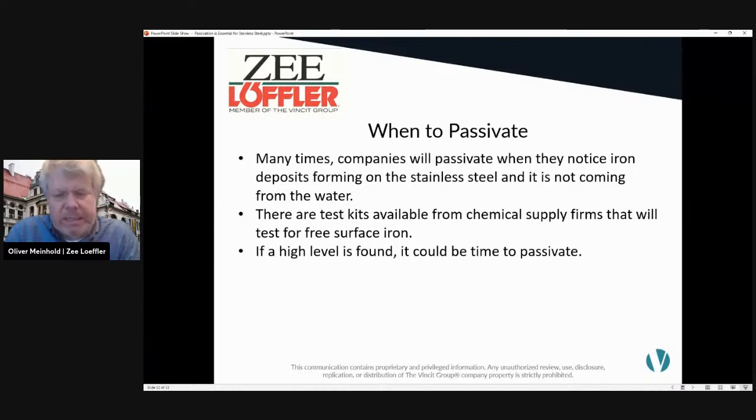We have customers who opened their HLT for the first time after 2.5 years, found a lot of scale, cleaned it out, and then had to call the manufacturer and were told that this tank is not fixable and a new tank has to be put in, because the corrosion reached a degree where fixing is not possible anymore. So like I said, a very aggressive area is the HLT because of varying parameters: heat, scale, calcium, magnesium, chloride levels. Keep an eye on it and descale it on a regular basis. And then once a year, do a passivation on it. And your HLT will be very happy.